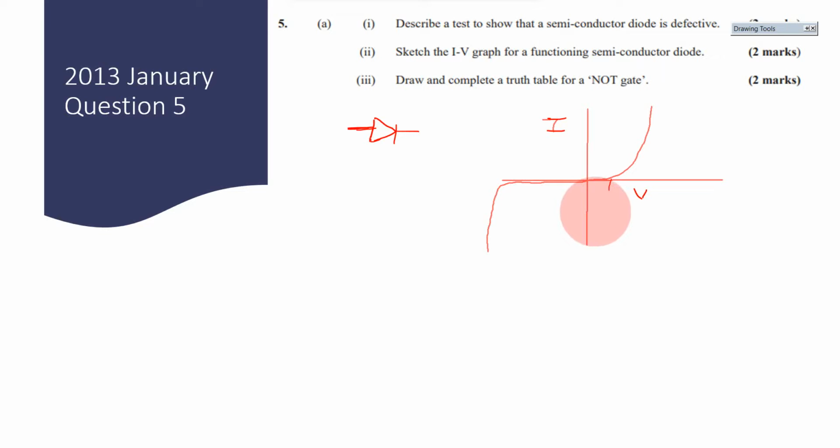Now, I could explain it to you. Now, when we think about semiconductors, they don't really allow electricity to flow as easily as you can imagine. So you need a little bit of energy, right, in order to excite the electrons in the valence band, in order for them to jump over the band gap where conduction will take place, right? So when you see us applying a small voltage here, it is to give these electrons energy so that they can jump across the band gap, so that they can conduct, right? So that's the purpose of this.